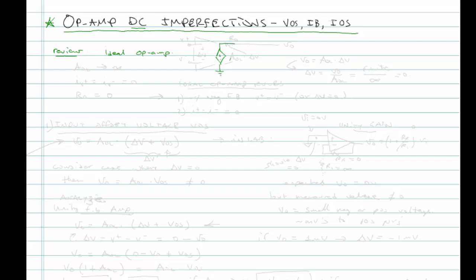So first let's go ahead and draw the equivalent electrical model. It's very simple. All it is is a controlled voltage source that's controlled by voltage delta V, with controlling voltage terminals V plus, the non-inverting input, and V minus. I don't know if I'm going to be able to make this look like an op amp, but here we go. And then we state from this that AOL is infinite for an ideal op amp.